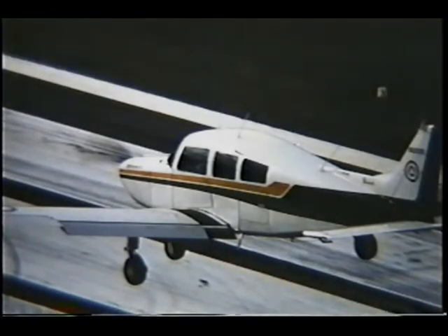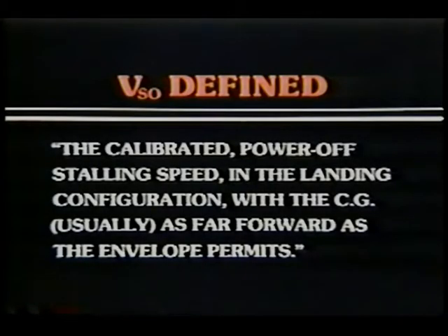If for whatever reason that speed is not known, then the rule of thumb is to set up a short final approach speed of 1.3 VSO. Now let's take time out here for just a minute to talk about what I mean when I say VSO.